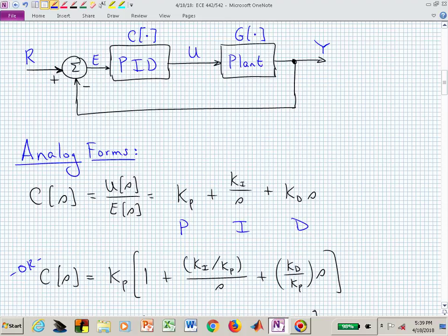Now you've put it into a form that allows you to adjust that gain after you've established the integral gain and the derivative gain. You can now adjust the gain outside, like in our typical block diagram for the root locus.